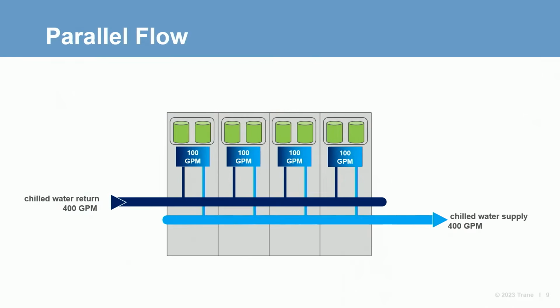Now, because flow is provided to modules piped in parallel, we need to consider how flow differs from what we're used to in a packaged chiller where the fluid stream has only one heat exchanger in play. Let's look at this even more generically. Each module is hydraulically in parallel with the rest. Every module has at least one refrigeration circuit, usually 2. Here the cylinders represent compressors.